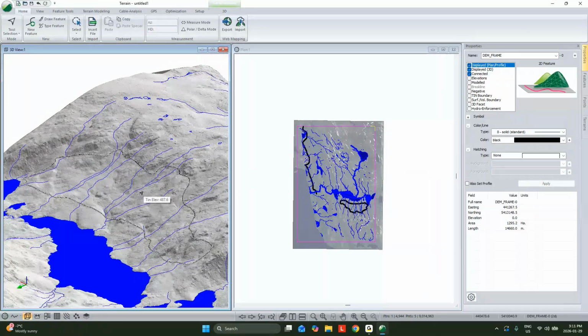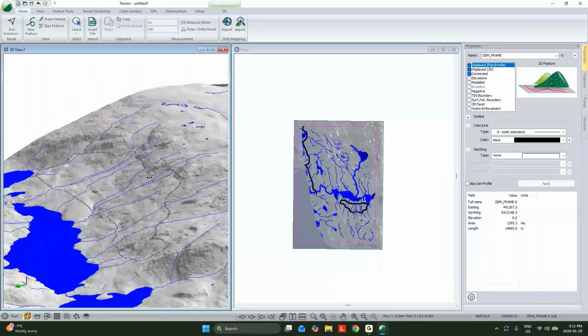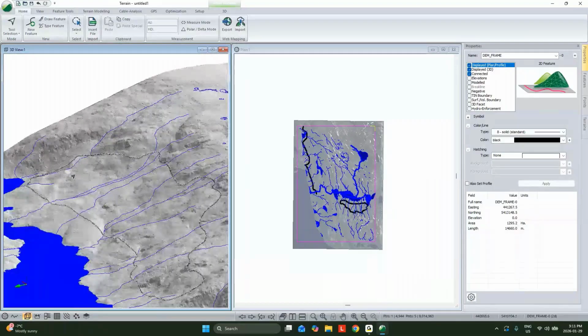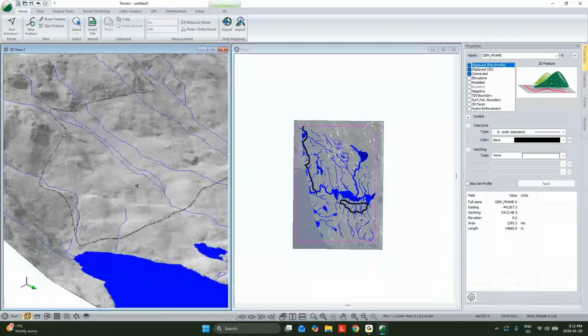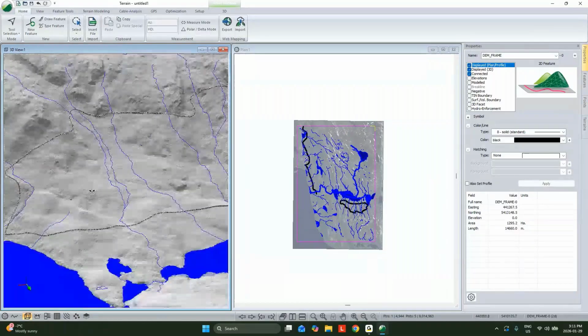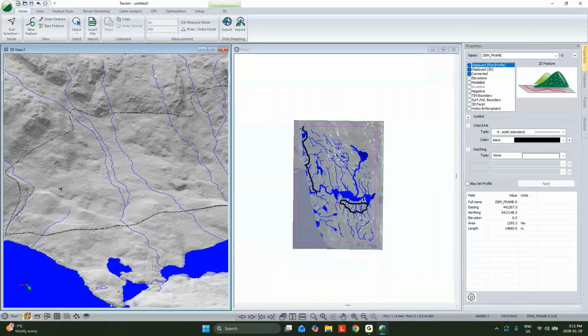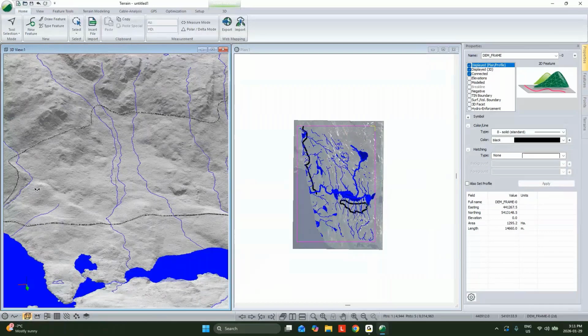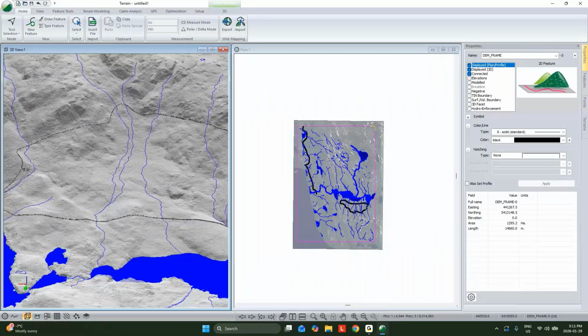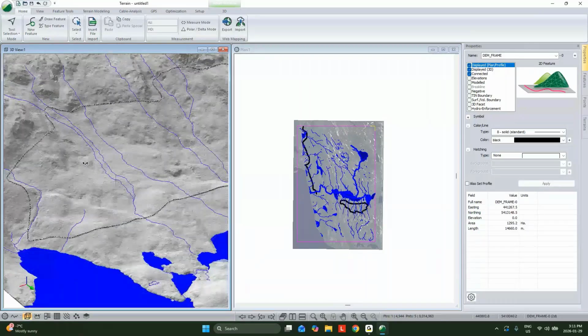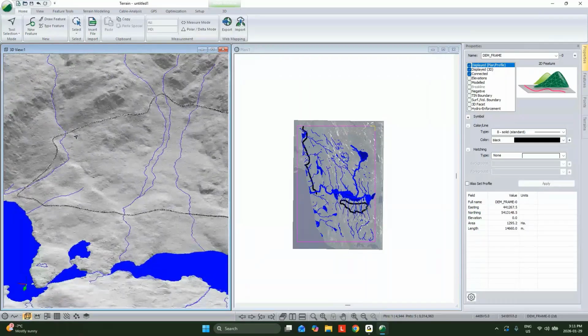I'm going to just choose my landing location based off of operability and forwarding distance. So with that, I probably have a maximum preferred forwarding distance. But I'm going to push my road near the end of my block, coming out to the boundary, just because this is on the verge for whether we can tackle it with ground-based equipment, and I don't want to have my guys running a side hill.